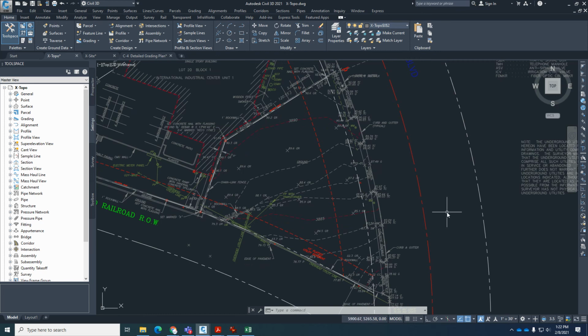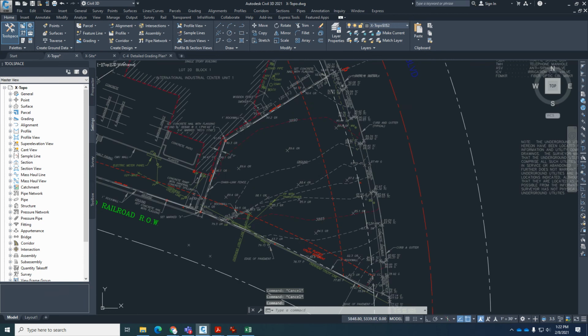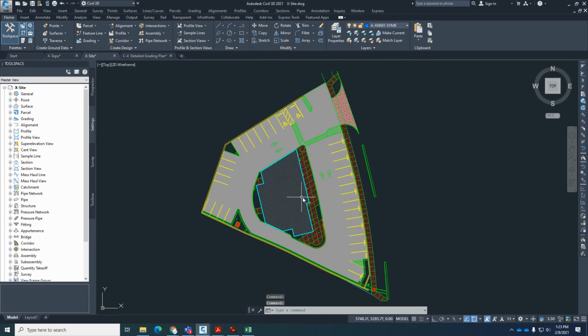So again, that's why you as the civil engineer need to use the real topo. You have to use the one with the actual property lines, and hopefully the architectural site plan fits. And sometimes it doesn't. Sometimes you put it together and you've got a parking lot that's maybe sticking into the next door over here, or the driveways down the line, or just all kinds of things could happen. But nonetheless, that's how that works as far as why we have that little competition between architects and engineers, because they use different methods of developing site plans and stuff.